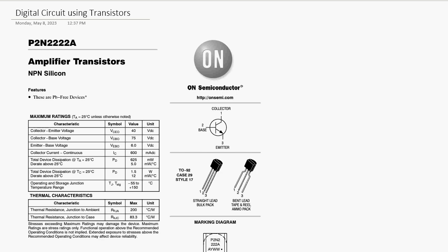So first we've got a transistor here for demonstration, which is this transistor. And you have to pay attention, this is not like usual. This is a collector, base, emitter. The right face, this is the left face. So 1 is collector, and 3 is emitter. Okay.